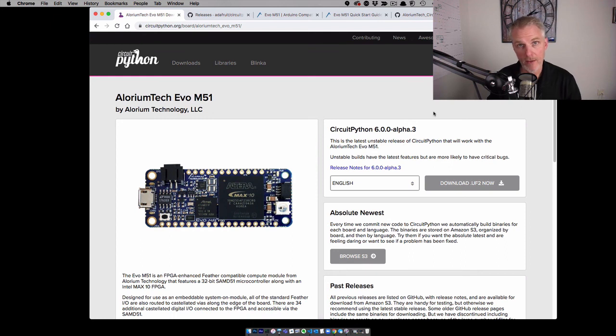Well, as it turns out, there's a change in Alpha 3 that breaks our I2C calls. Remember when we talked about how we've got this interface between the SAMD and the FPGA? The way we actually configured the FPGA is across the special I2C bus between the SAMD and the FPGA that sets the inputs, sets the outputs, and handles all of that.